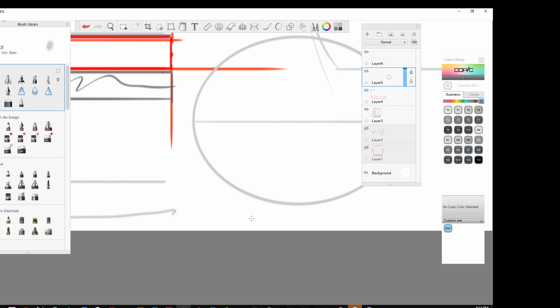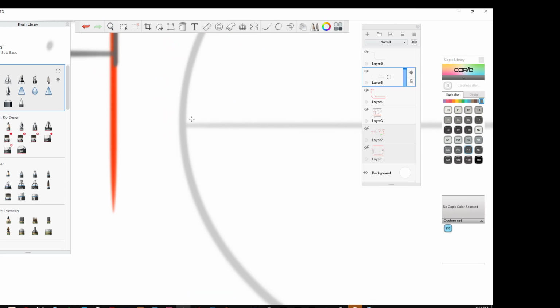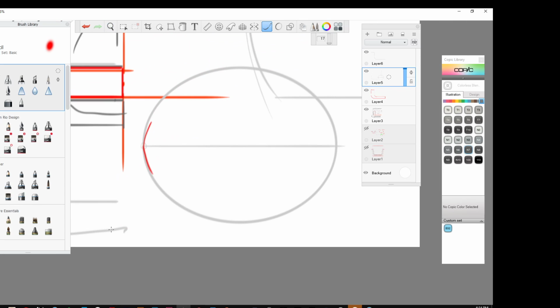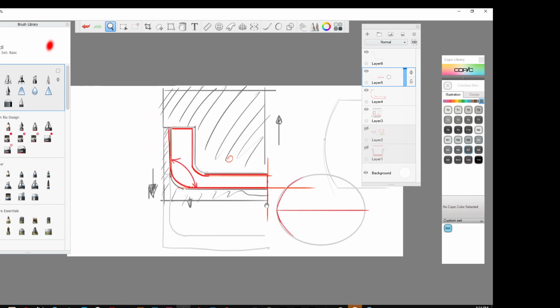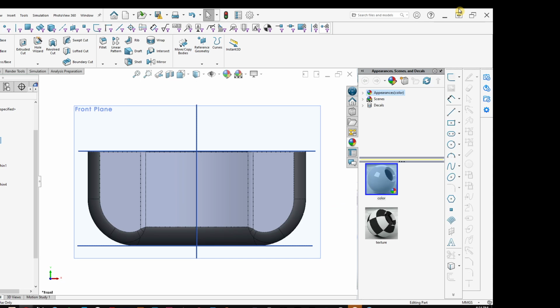But if you've got a circle, it can't be perfect like that because there's zero draft there. So what you have to do is the circle's not really a circle anymore, because you need to have it start at a certain draft. Now, depending on how much you can push it, let's say this is it, there's got to be that little break in there. Okay, so now that we've got this,